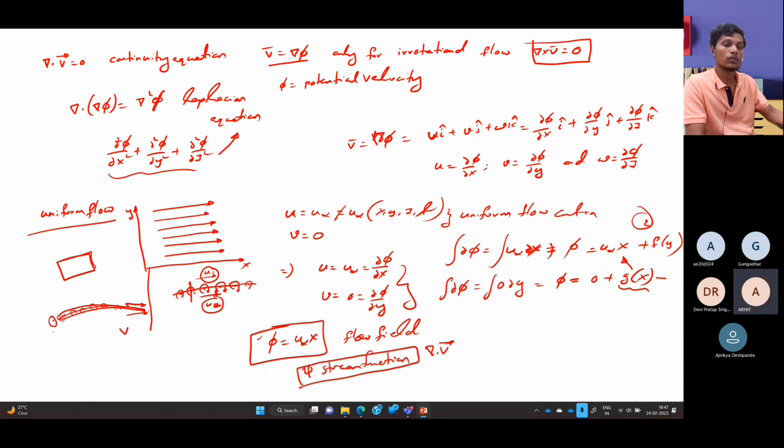Sir, actually, I think in the Kutta condition they are taking incompressible inviscid flow. That's why at the leading edge there is a stagnation point. In the professor's lecture I saw the flow field in a cylinder, the concepts of doublet and the combined flow of doublet, vortex point, and uniform flow. In that, the flow separation does not occur in the incompressible flow case.